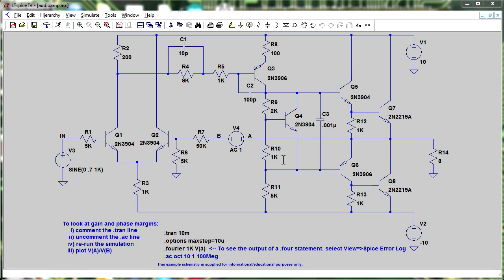SPICE simulators out of the box are not entirely optimized for the top level stuff, which most people use it for, the board level stuff, your op amps, your switching regulators, and all that sort of thing. Out of the box, a lot of the time, it won't converge or be able to solve your particular circuit.